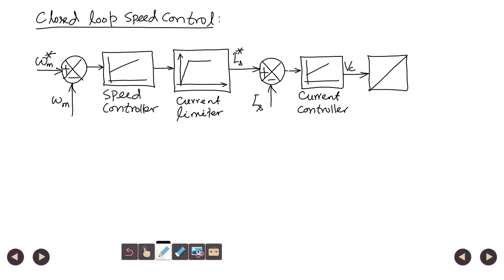This Vc is converted to alpha for the firing circuit of the voltage controller. So, Vc to alpha is converted and alpha control is done for the 3-phase AC voltage controller.